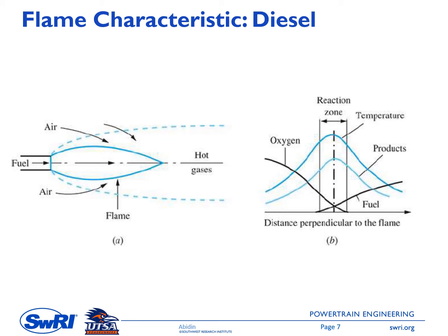This vapor is produced due to the evaporation of the liquid fuel drops, and this fuel vapor flows into the inside of the flame. So this is the flame front. Let me put it here. This is the flame front. Then a chemical reaction occurs where the temperature is highest.